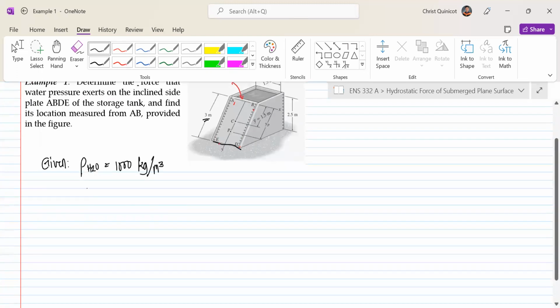So our plate, we can write it as, plate is rectangular. Now, why is it important to assess what plate that is? It's because whenever we will find the value of the y or x component of our center of pressure, we will be using the moment of inertia, right?